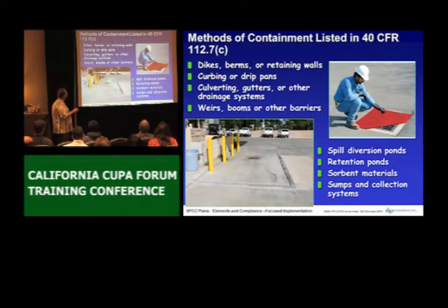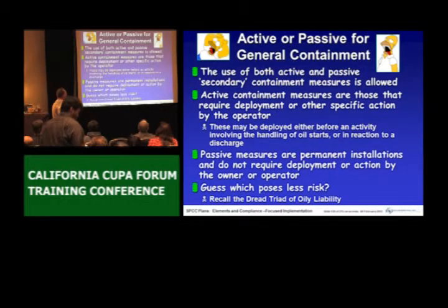You know, this is a loading area. That's a 3x3 dead sump, or 2x2 dead sump, little curbing. This is the tank and secondary containment, closed drain valve. Is that their general containment for the loading and unloading? Pads, either before a spill or in response to a spill. Be careful about your active measures. You need to be able to implement them, drill and train on them, and make them credible.